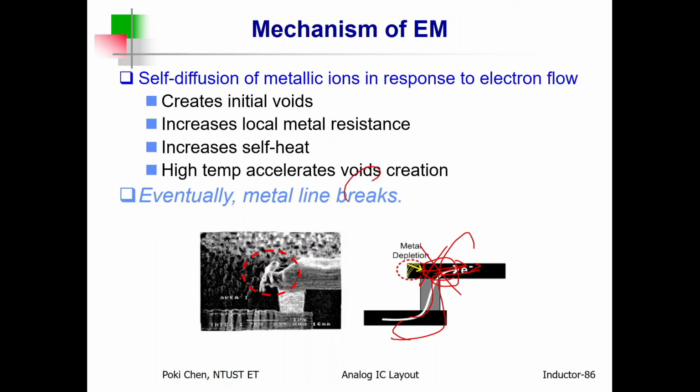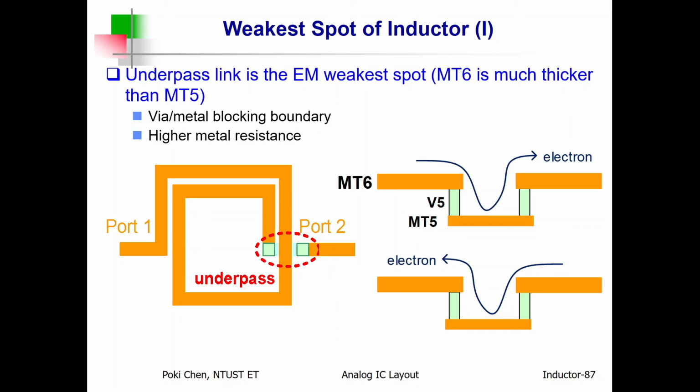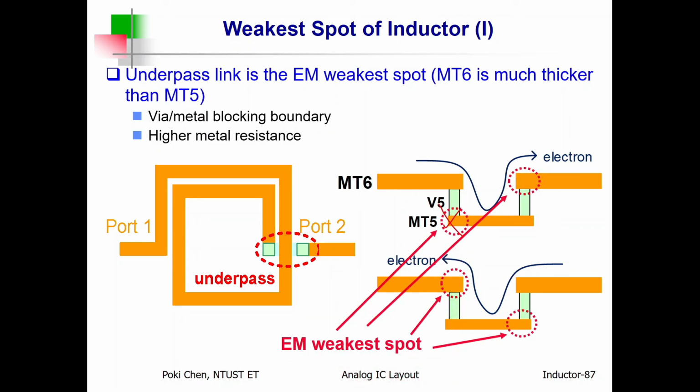Eventually, the metal line breaks. The RF chip simply becomes malfunctional, or it doesn't work at all. Right? All the cost needs to be fully covered by Intel. Anyway, if electrons flow in that direction, then you will face the serious impact from metal migration here and there. On the contrary, if it flows reversely, then here and there needs to face the challenge, right?